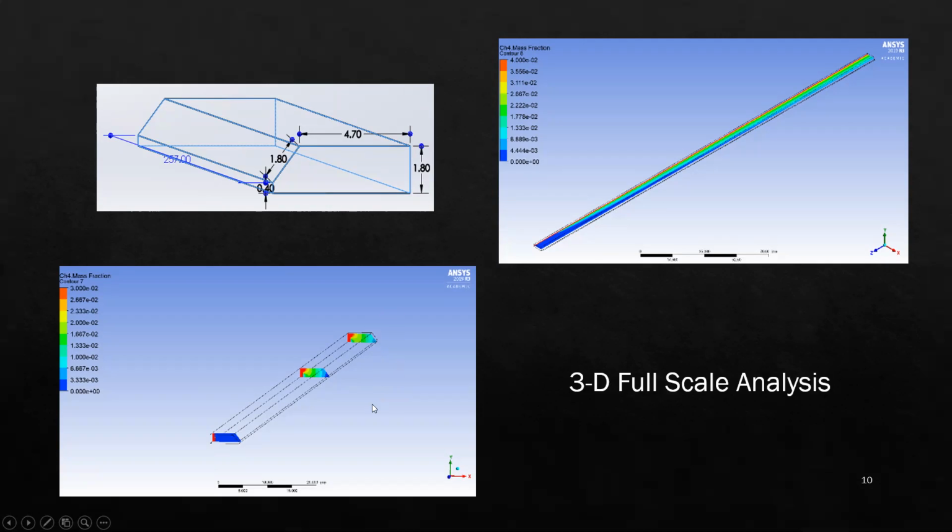I have this now, I have the only source of methane being released from the face. So we're saying here that we're assuming that methane is only a function of cutting coal at this point. Realistically, it's naturally being desorbed from the coal all around. So really there may be some type of methane flux everywhere. But we're saying that it's just a function of cutting the coal. So I have it defined as this face.